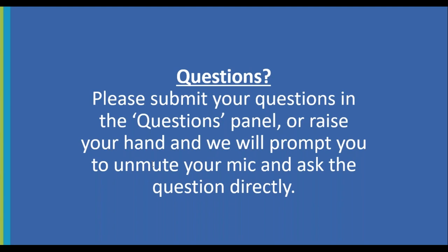So if you're looking at a chunk of wood, usually, let's say you're running 50, 100 milligrams of sample, and it's a tiny square of 0.5 centimeter by 0.5 centimeter. We usually recommend to maintain that type of measurement. We have systems that run parallel experiments, so a high throughput system in which you can load 5 samples at the same time. And what we usually recommend for this type of experiment is, in general, having an average of similar mass. So if I'm loading 50 milligrams of sample, I would prefer to have samples within plus or minus 10 milligrams between the 5 experiments.